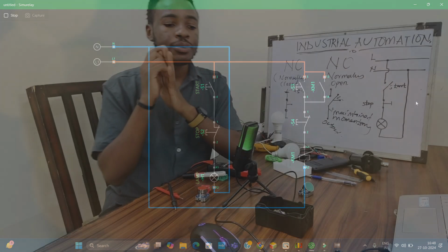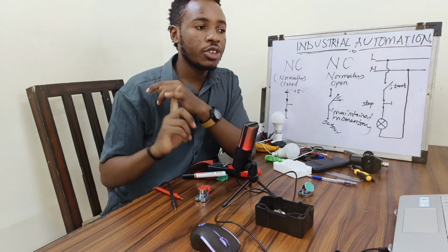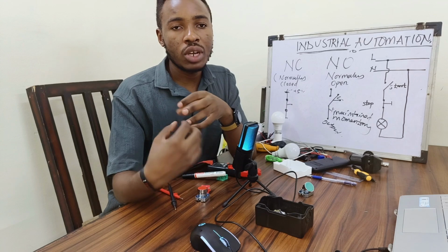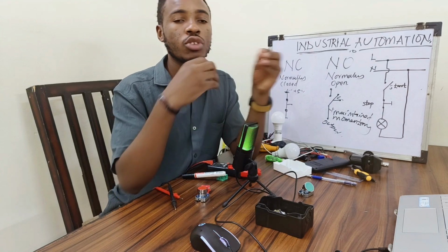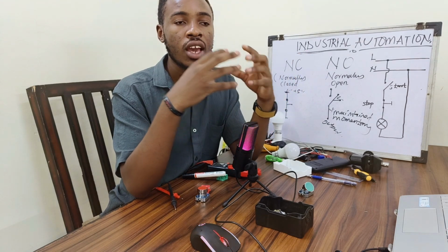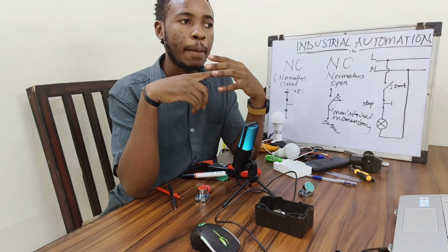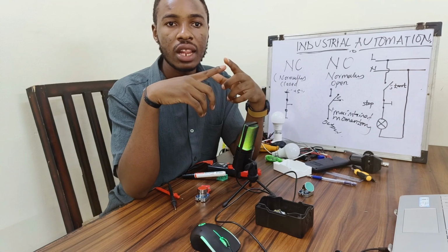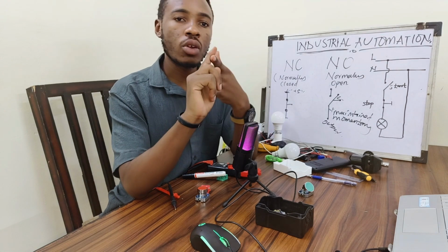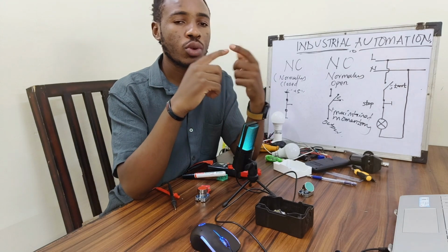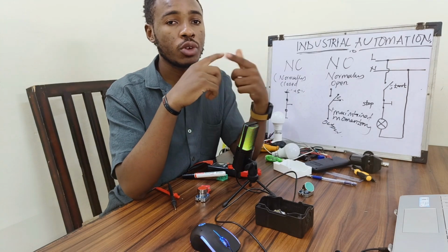Basically, you can implement this without using a PLC, but what I was trying to bring to you is the attention to the momentary switches, the whole concept of momentary switches, and how you can do the latching and hold on. In control wiring, you will find people calling it hold on, and in PLC, we call it latching.